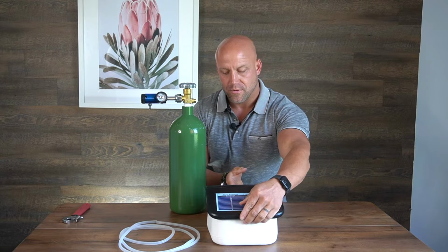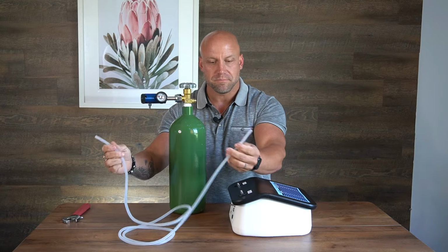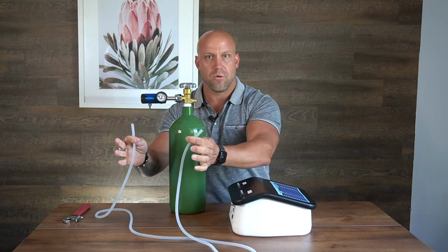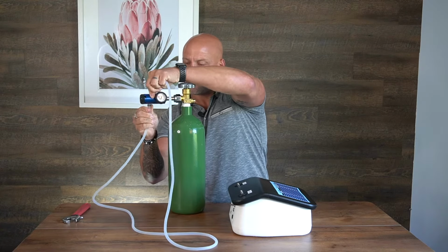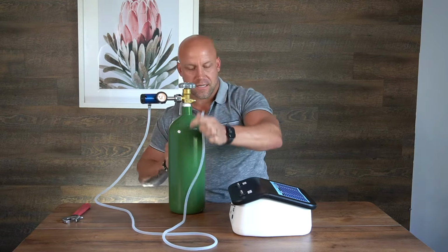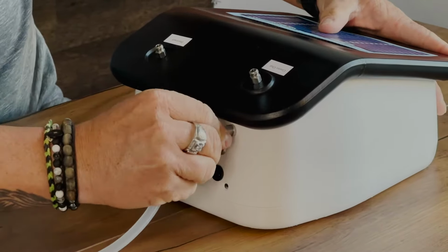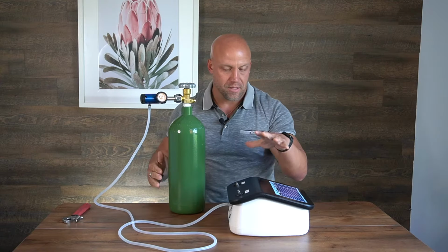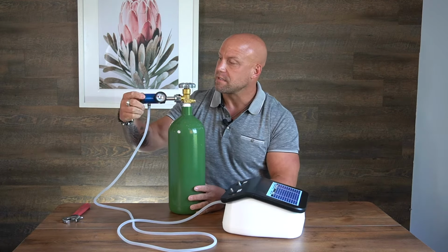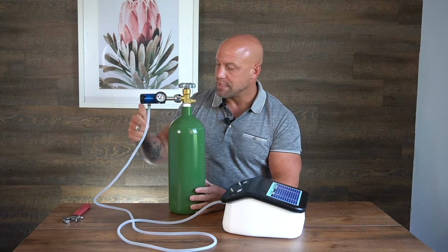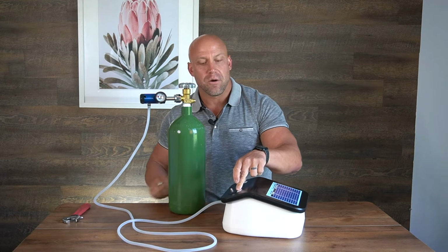As we discussed before, our generator has an oxygen input. So what we take is our silicone tubing. We can see we have open ends on both. We want to insert the tubing on the regulator, just like that. Make sure that it's all the way up and tight. And then you take the other end of the tube to the oxygen in. Once we have that in, the ozone generator is not on at this point. If we were to open up our oxygen tank, which we open up, right now only oxygen is flowing directly in here, and only oxygen is coming out of the ozone output.